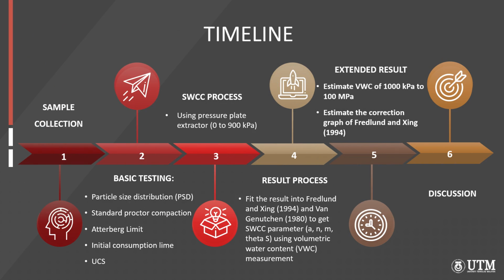This is the timeline to conduct the study. Firstly, the laterite soil was collected at P16 in UTM Skudai. The soil was transported to the geotechnical lab to run several basic tests such as particle size distribution, standard Proctor compaction, Atterberg limit, initial consumption of lime, and unconfined compressive strength. After all basic testing was done, I proceeded to do the SWCC process using the pressure plate extractor.